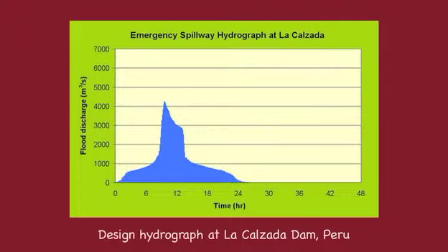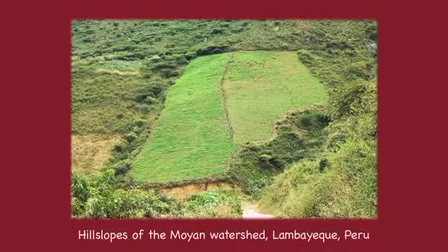Catchment response refers to the relative concentration and timing of runoff. A faster response leads to higher peak flows. Conversely, a slower response leads to lower peak flows. Other factors such as relief, vegetative cover, and drainage density are usually more important than shape in determining catchment response.